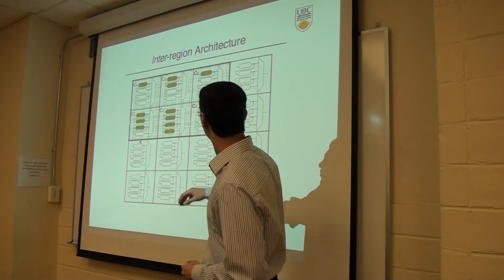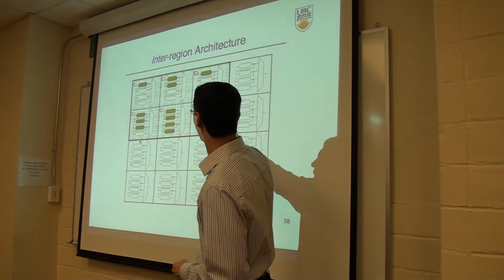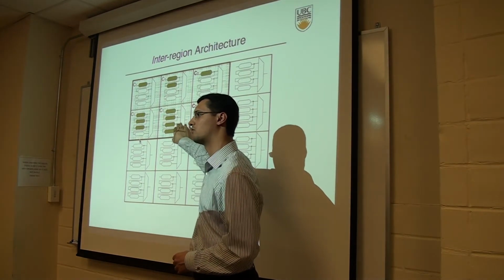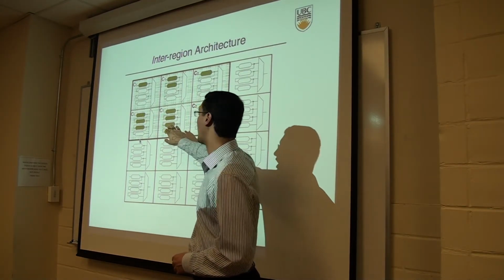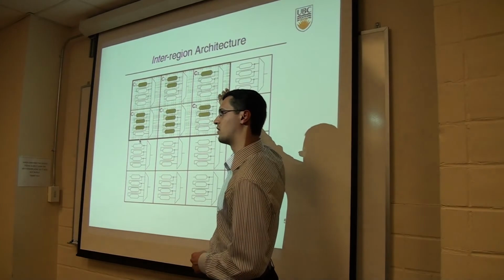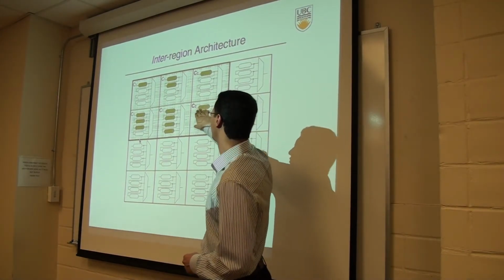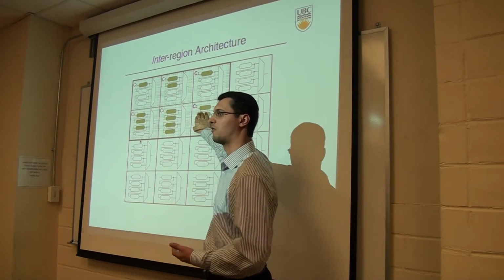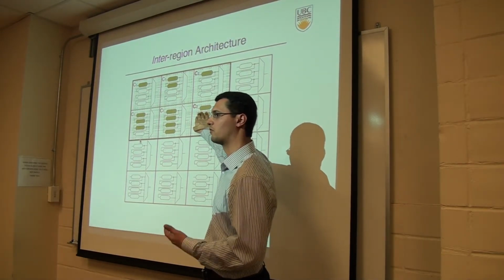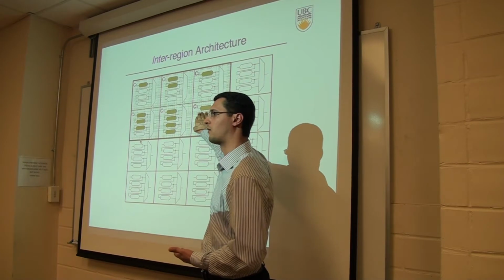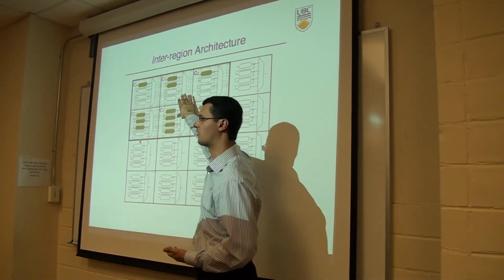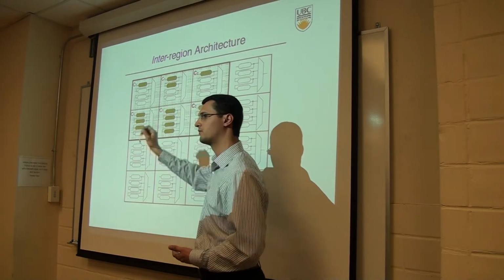Okay, so basically here we have four regions that are controlled using one control signal, which is C1, and the extra two regions in this application are controlled using another signal, which is C2, that's delayed from the power controller that generates these signals. So the power controller should provide the power delay to sequence the wake up of these two regions after the wake up of these four regions.